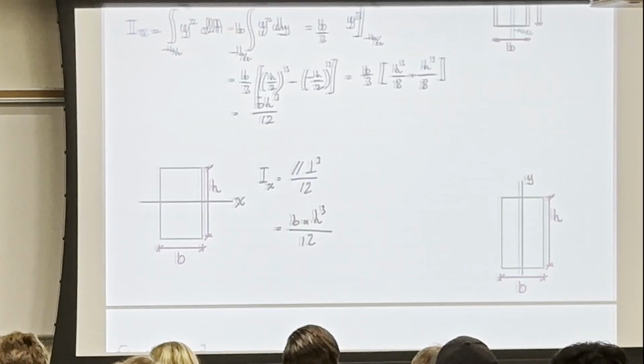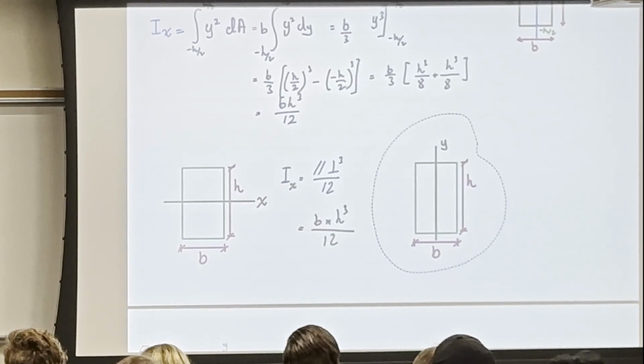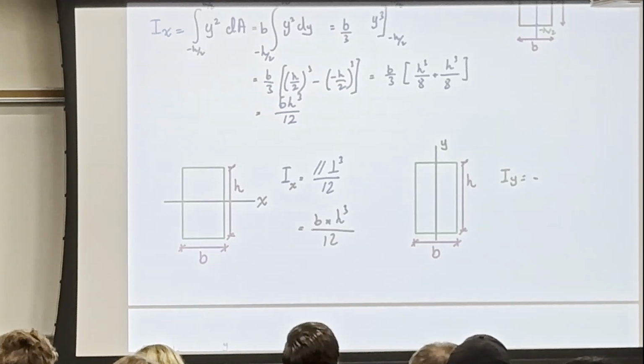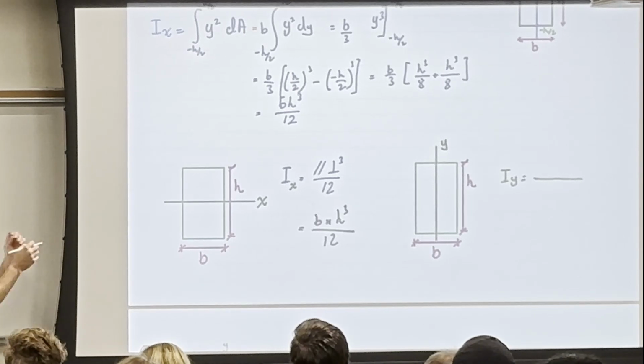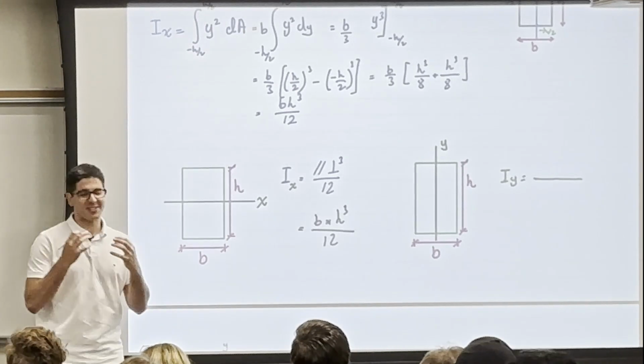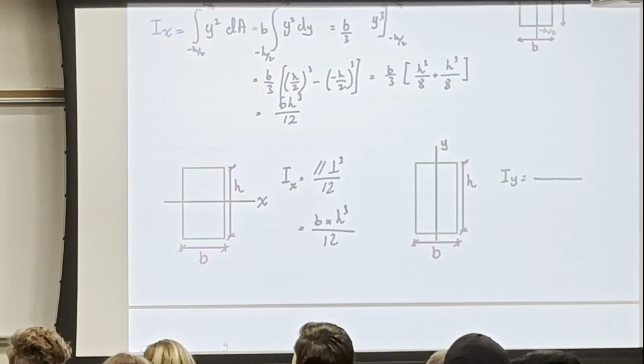So that's if I want to find Ix, and now for Iy, now you tell me: parallel perpendicular cube over 12. Always memorize this. I just translated from Arabic to English, but in Arabic, it's like there is a symphony when I say it, but in English, it's a little bit hard, but I think it makes sense. So parallel perpendicular cube over 12.